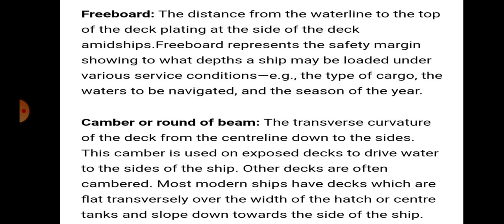Freeboard represents the safety margin showing to what depth a ship may be loaded under various service conditions. For example, the type of cargo, the water to be navigated, and the season of the year. All this depends on the freeboard of the ship.